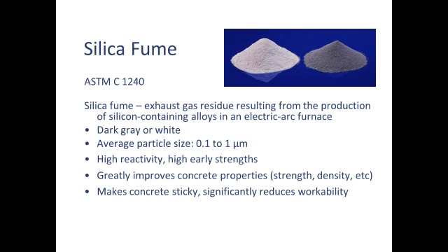You get very high reactivity. But the trade-off is it can make your concrete very sticky if you use it in high quantities. So it's described as having a very high water demand. Again, that very bad habit of using water to change your workability.